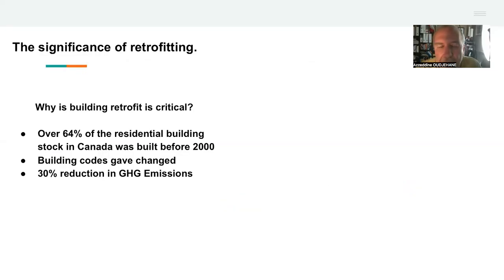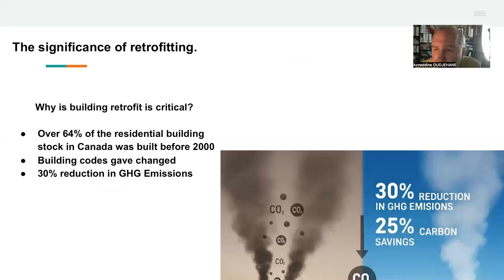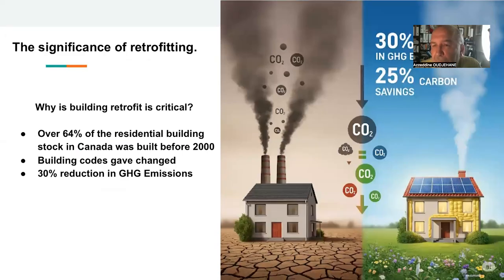needing upgrade and update. So the building stock is large. The opportunity to reduce GHGs when you retrofit the building is tremendous: at least 30% of GHG reductions by retrofitting the building envelope, the windows, the roof, the energy system, and so on. Depending on the retrofit that is done, it can reach up to 50 or 60% reductions of GHG, making the existing building almost carbon neutral.